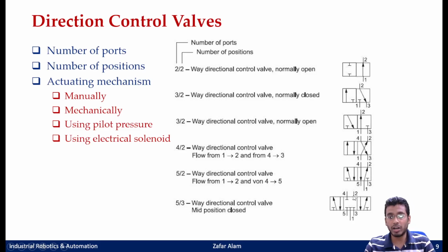Your numbering is actually only on the default position. For example, whatever is your default position, in that position you will number. The left and the right positions would be your engaged positions with the same number of ports. So if you talk about this 5/3 valve, what is the default position of this valve? It is the center position. The positions which are not numbered will also follow the same pattern as the numbered position.